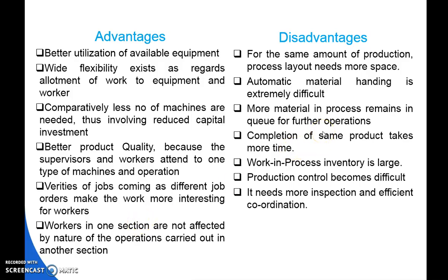But the disadvantage is that this process layout needs more space for the production system. The material handling is extremely difficult. I have already told this during the explanation of the process layout. More material in process remains in queue. We have seen that the path from one department to another is long. Hence, there is a waiting time for the material in process.